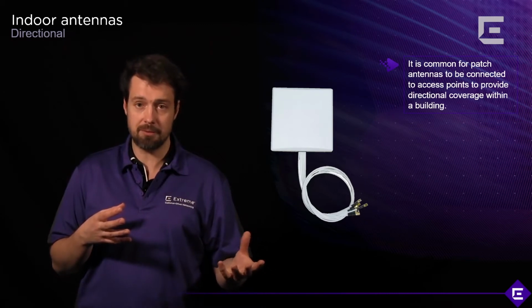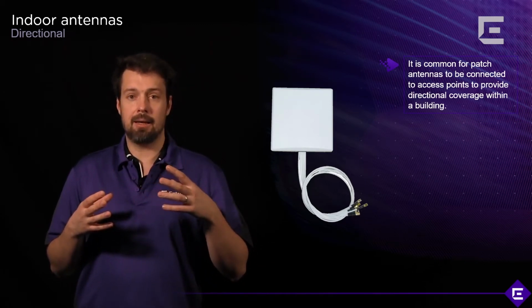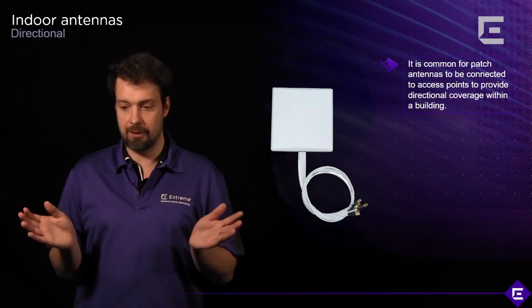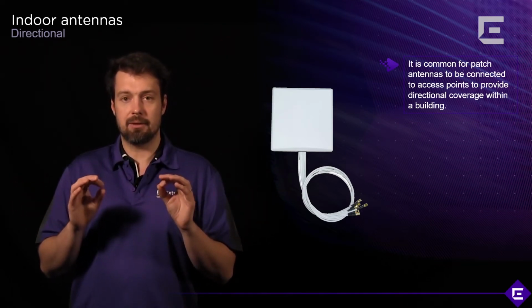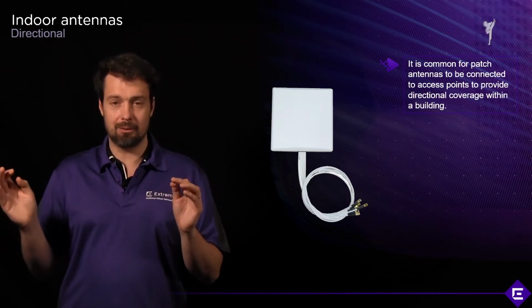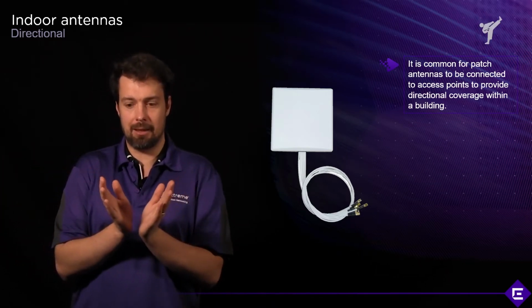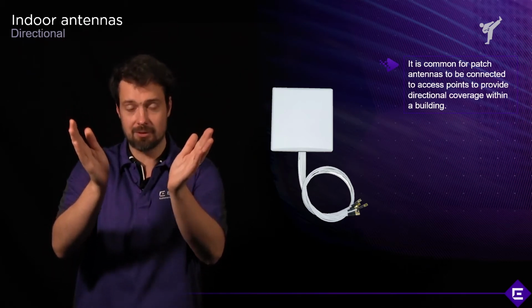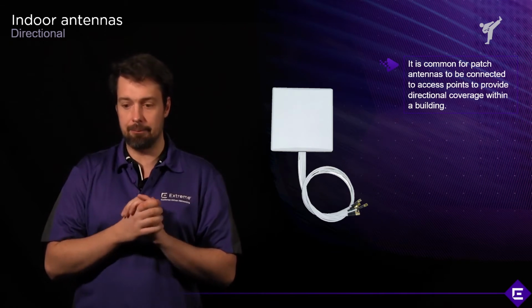There are different types of directional antennas, and like all antennas, they will differ on what frequency band they support. They will differ in how they direct the signal. We call this how they attenuate the signal, or most often it's going to be determined by the signal radiation pattern, which will show you in what direction, in terms of degrees, the signal is directed.